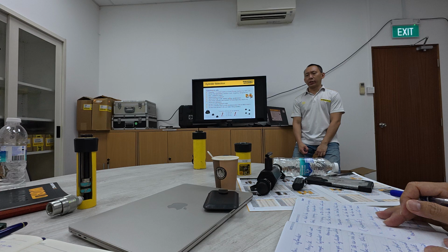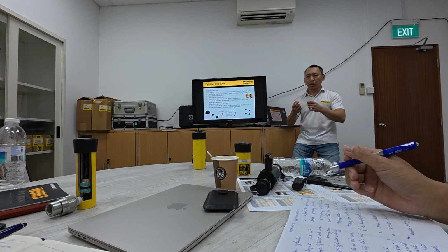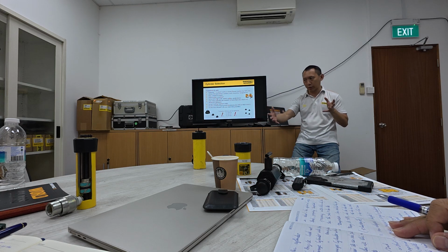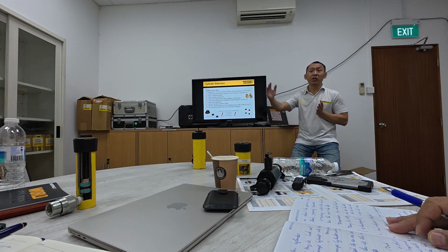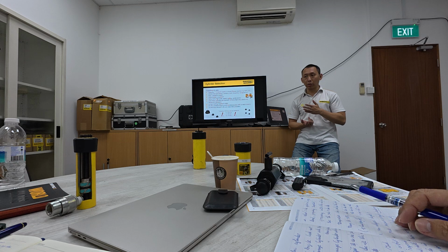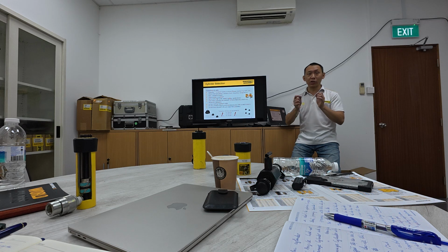For example, if in 1 hour you need to advance and retract, maybe every 5 minutes you need to advance and retract, I would say that's high frequency. But then again, if you are doing this at low pressure, maybe the customer is not using the maximum pressure of 700 bar, maybe they are using about 100 bar or 200 bar, that one maybe it can work. Because it really depends on what type of environment and frequency as well.